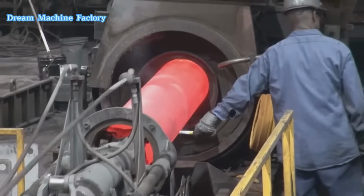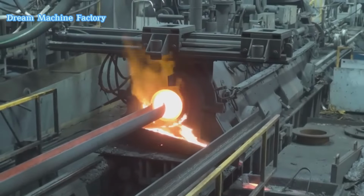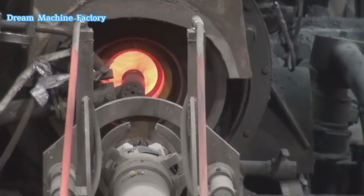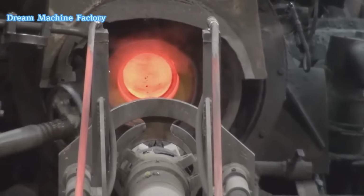After the pipe fully solidifies, it is extracted from the mold, and the remaining sand core is broken up and removed. The hot pipe is then placed on rotating rollers to maintain roundness and straightness before moving to the annealing stage.